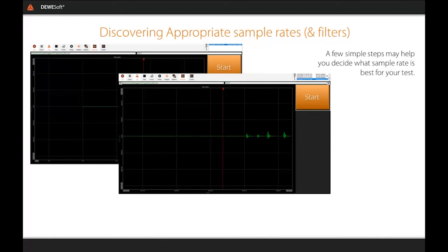We want to see what frequencies are involved in that propagation of the wave as it passes through the specimen. Again, you could repeat this step across connected components to gather information about the coherence between them. It could also demonstrate where dampening might improve the behavior of a test object, but we'll cover all of that in a seminar on modal analysis later.